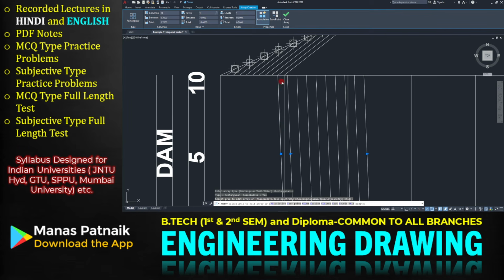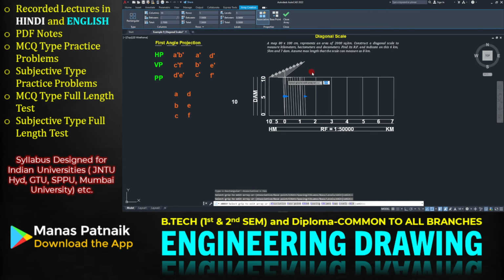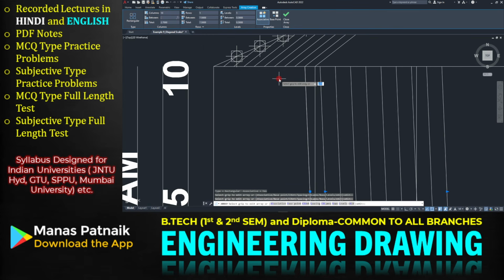One thing that you observe, we need the rectangular arrays to the left. It is giving me to the right. So instead of having the distance between columns as positive, let us take it as negative, minus. But what is the spacing going to be? Sir, we know that this is 2 centimeters. 16 centimeter was original. So each of this block is 2 centimeters. So 2 centimeter divided by 10 will give you 0.2.